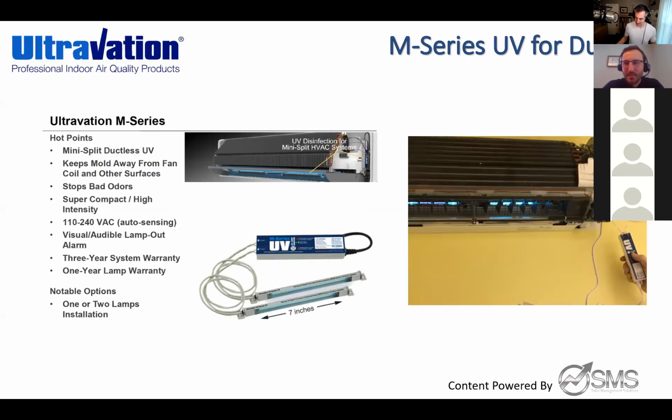Next is the M series for UV ductless. This is an extremely cool product. This does do the UVGI. We went over the UVGI technology, and that's what ASHRAE recommends to kill bacteria and viruses. And this is what we have to do that for mini splits. I know there are other products out on the market for mini splits that do other types of technologies, but they do not do UVGI. We're focused on doing UVGI technology in the mini split here.